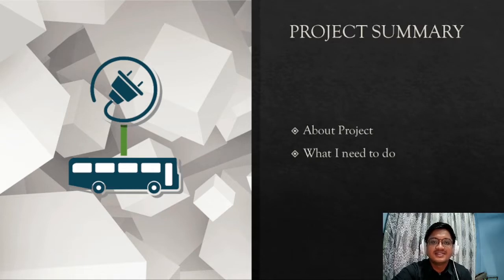The UN ECE Regulation Number 66 is one of the safety requirements that will be included in the design. The rollover crash analysis will be performed using finite element analysis, and the modeling and designing process will be using SolidWorks, while the analysis of this project will be executed in Abaqus.